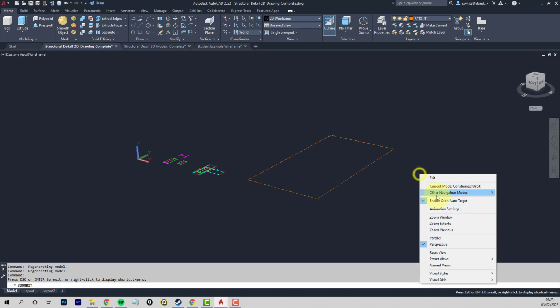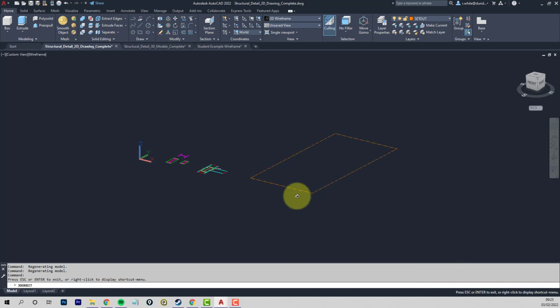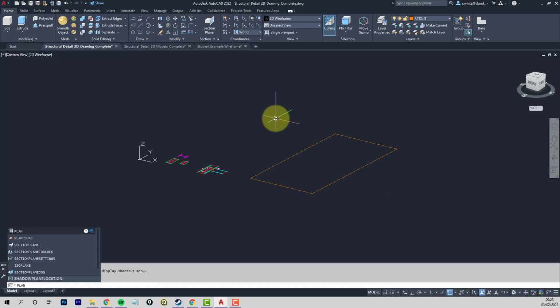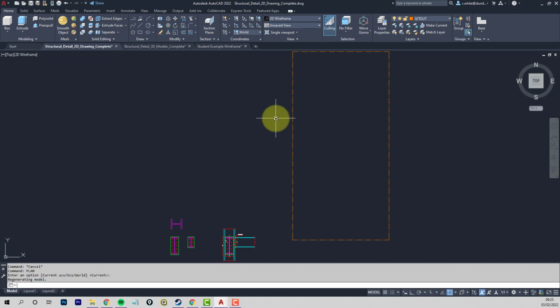Generally we work in the parallel projection, and that's much better for telling when things are stacking properly. It's easier to see if you're moving vertically or downwards whether things are in line with each other. And generally the buildings tend to be a stack of objects, so it is really important that things line up and down. If you want to go back to normal, you type plan and enter twice. So I'll escape the orbit command, plan, enter twice, and that resets everything.